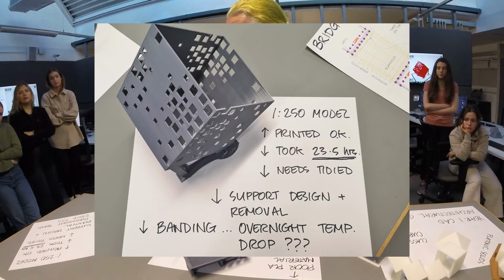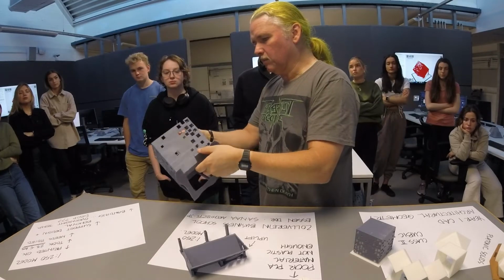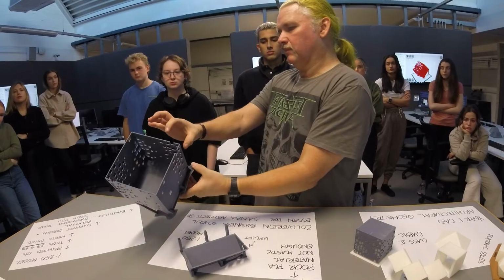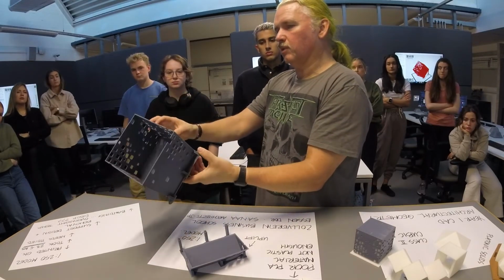So finally got one to actually print properly. But as you can see, these bits are breaking off, so you wouldn't tidy those up. But there is a bit of what we call stringing going on. It's a bit shabby inside, so a bit of tidying up. And one thing I didn't notice until it's finished is there's a change in the way the print is behaving about halfway up.